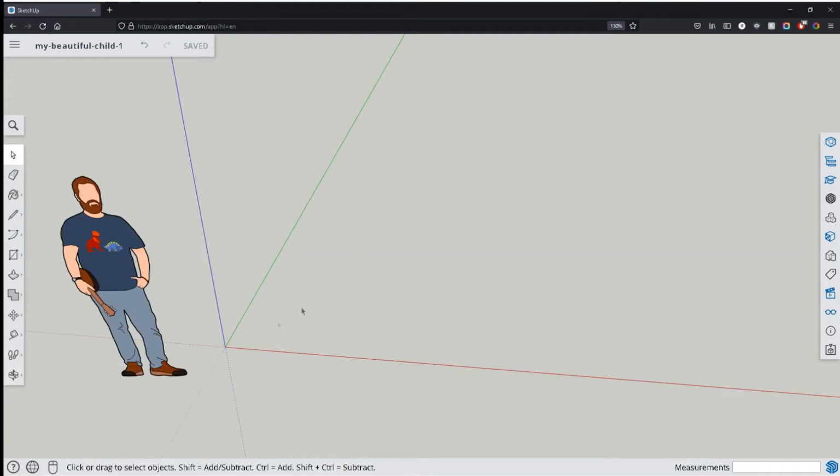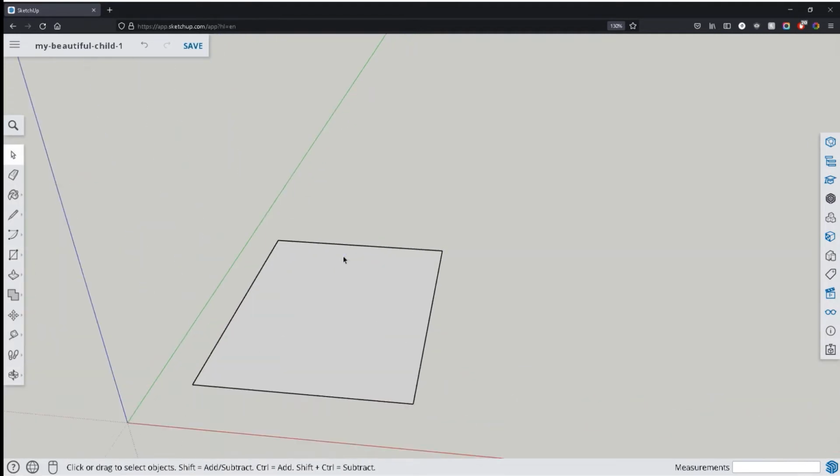SketchUp Properties. The modeling area is where we will be modeling. Here you'll see empty space and a 3-way axis, nothing else. Let's talk about guidelines and axes. When drawing, we can see dotted guidelines to help us stay on the axes. We can lock our guideline direction while holding Shift.